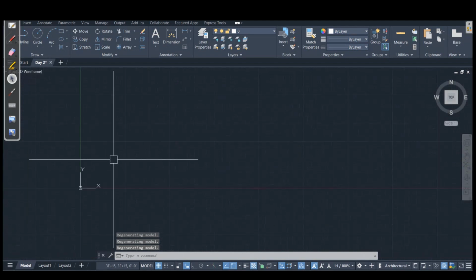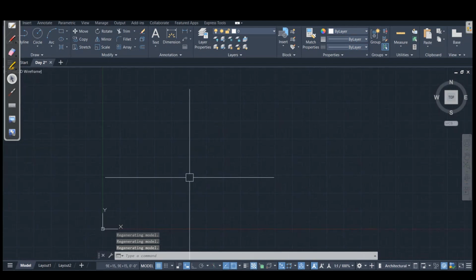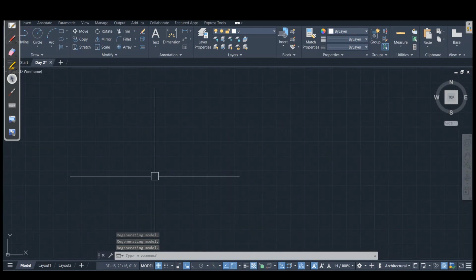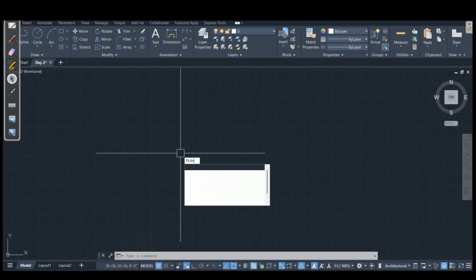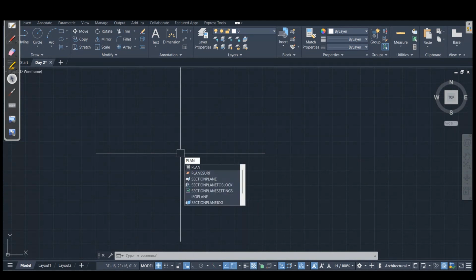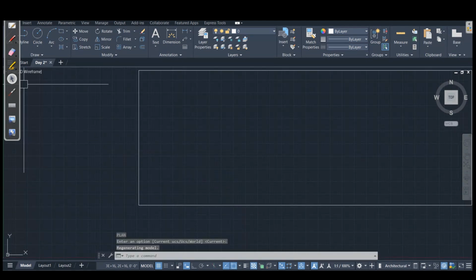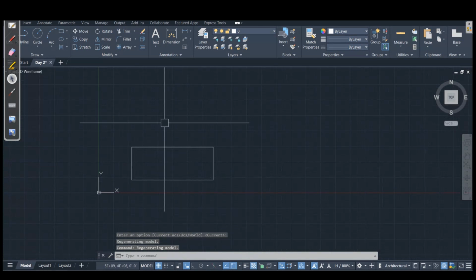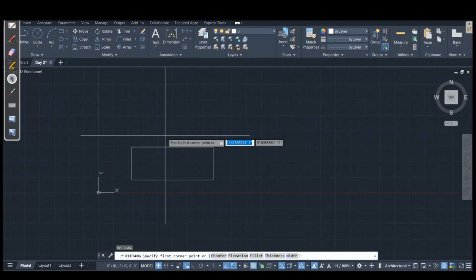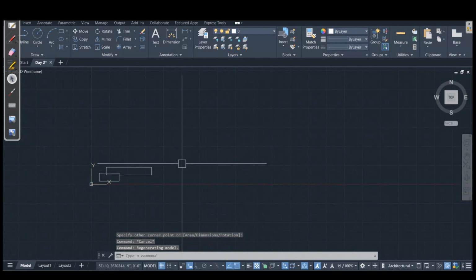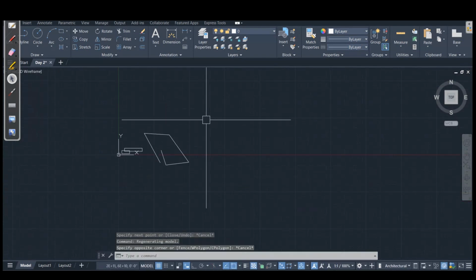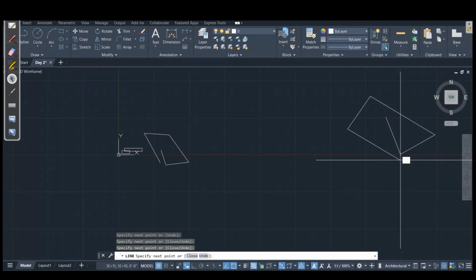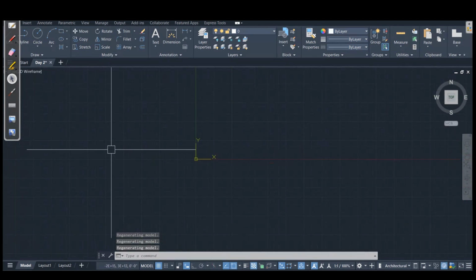If your drawing has disappeared like this, no need to worry. You just enter PLAN and press enter twice. Now your drawing is shown. However much drawing you have done, it doesn't cause any problem. If your work disappears like this, it will show all of your work.